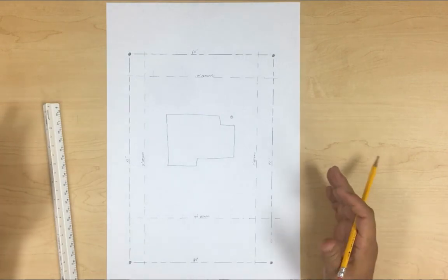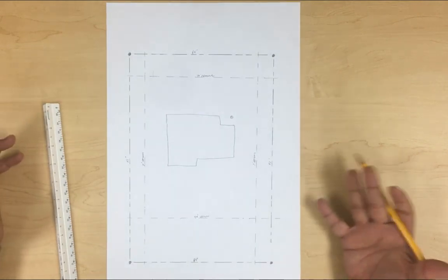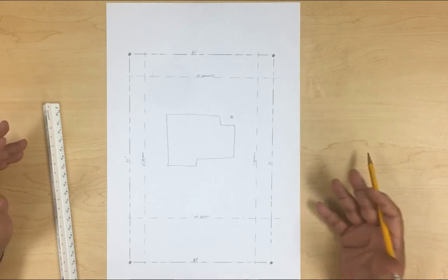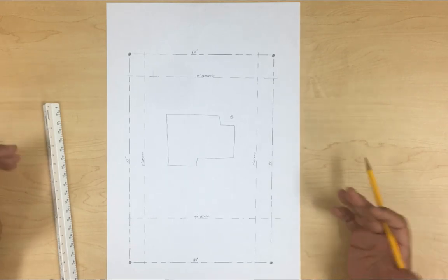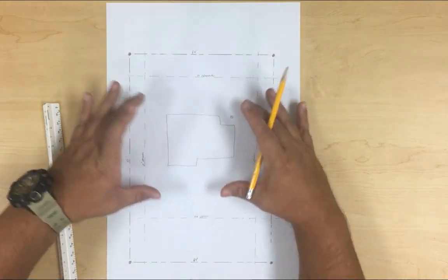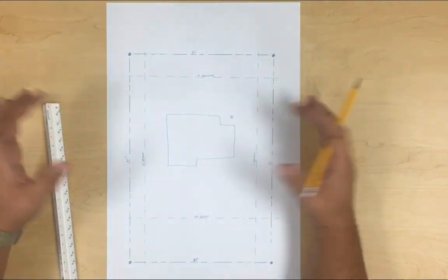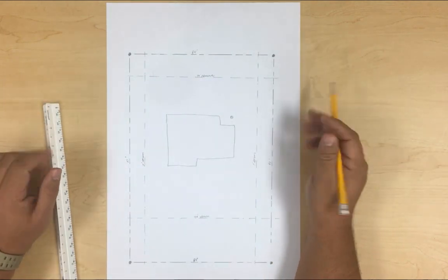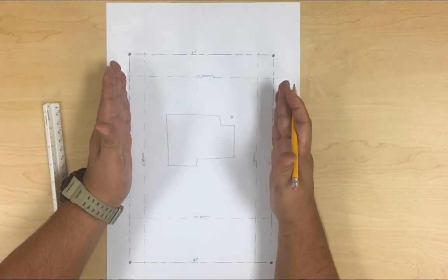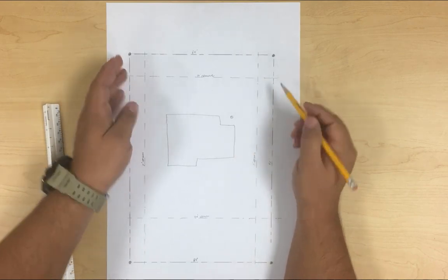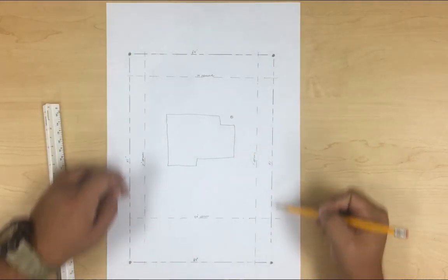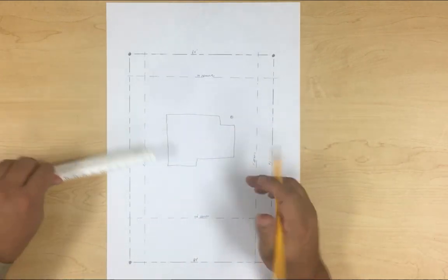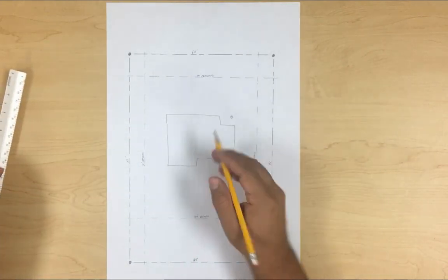Whoever's going to work with a foundation has to bring in some soil or take away soil, so you need to tell them where exactly you want it, so they can prepare the soil for the foundation. So we need to dimension that. Always tie a dimension to your property, because the first thing they're going to do is find your property, mark it, put the setbacks, and then from there they start measuring.